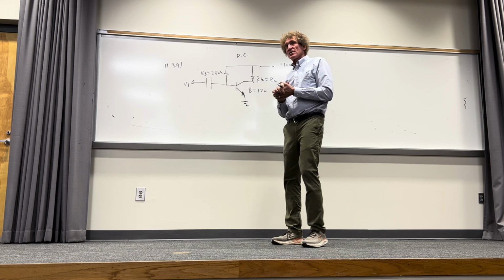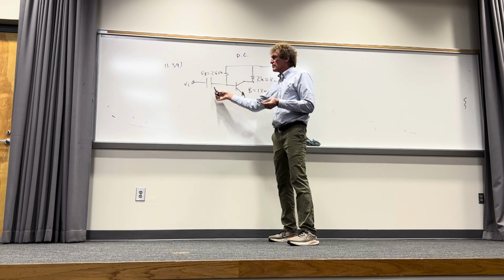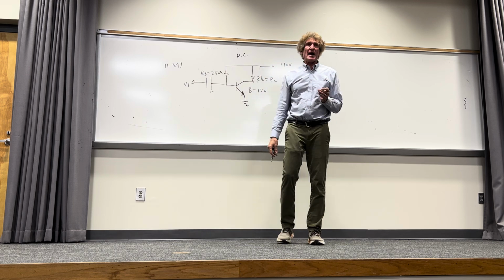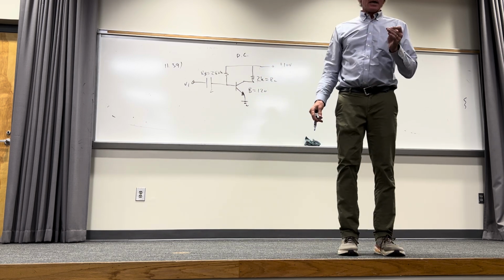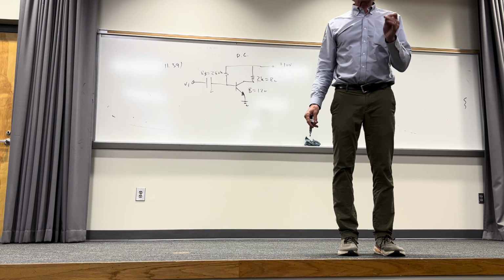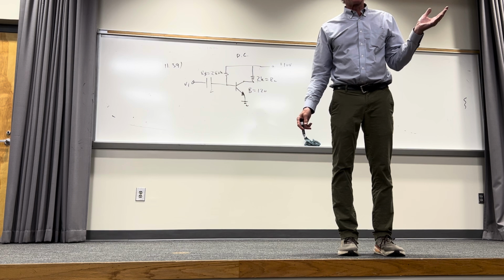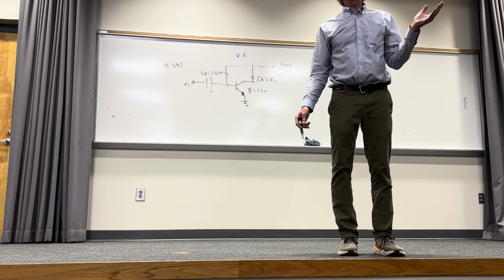I have a statement, I want you to listen to me. You see this capacitor right here? It really doesn't matter what the value is. What does a capacitor look like if there is no time varying voltage, if it's a DC voltage or a DC current? What can you replace it with? Anyone? An open circuit, right?